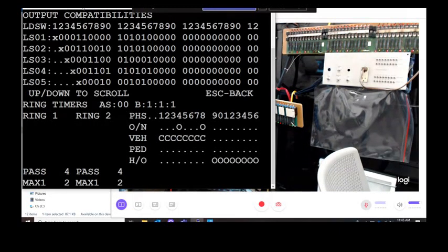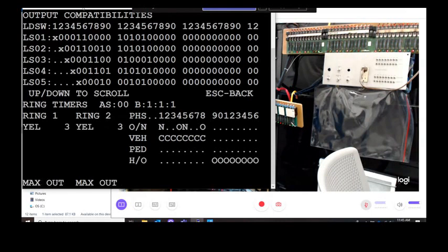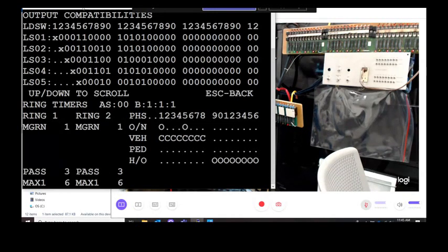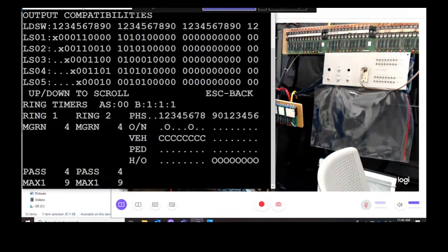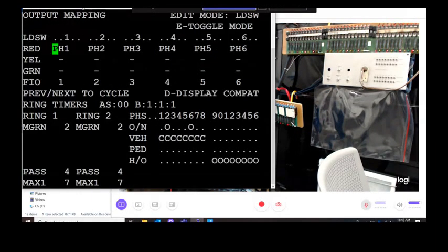So you can see where it says LS1, and then you go across. In this case, I have jumpers in 5 and 6, 11, 13, and 15. Wherever there's a 1 on here means that there needs to be that jumper in the associated card. If that all lines up, then it'll take off and run. If we're missing something, then it's not going to run. So go back and check that.